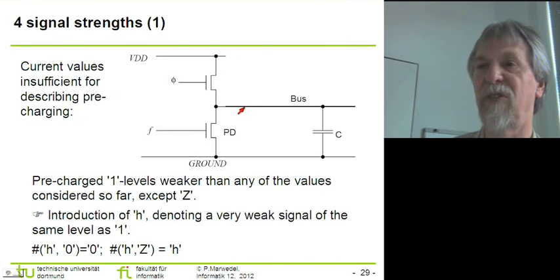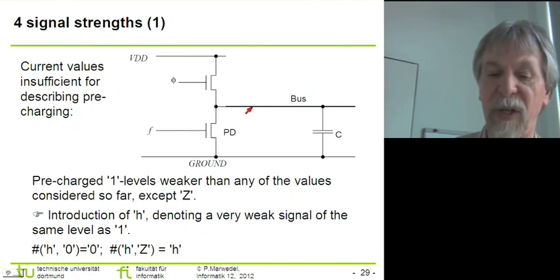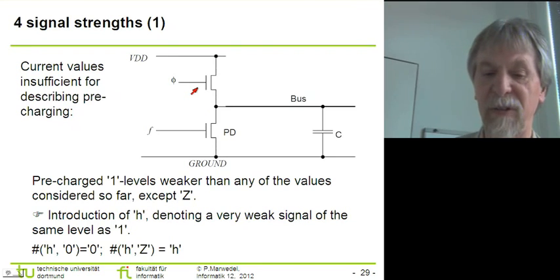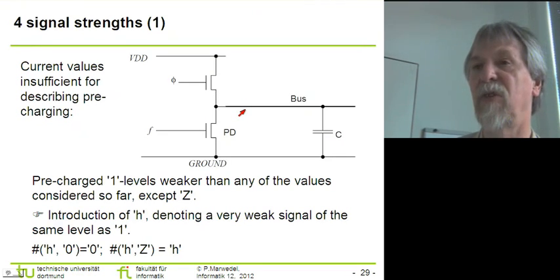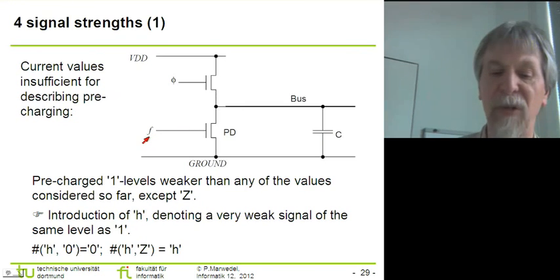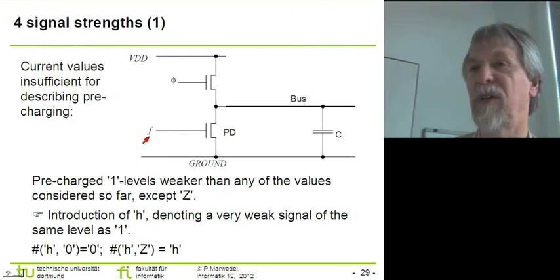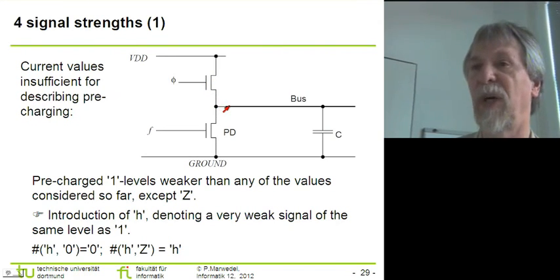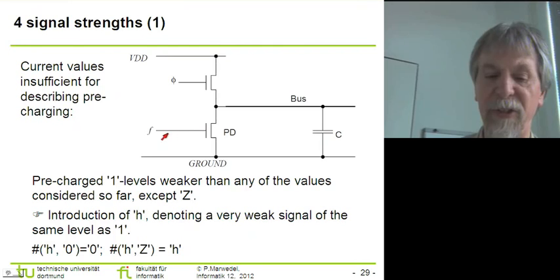Now we would like to avoid that additional delay in a rather smart way. And avoiding that additional delay in a smart way is possible with pre-charging. With pre-charging, we are adding a special circuitry to those wires where we see a very large capacitance. And in this case, we are pre-charging this bus during the times where we don't know the function to be computed anyway. So we assume that it will usually take some time to compute this function f, and during the time where we are still computing that function f, we are using those special transistors to pre-charge the bus to a logical 1.